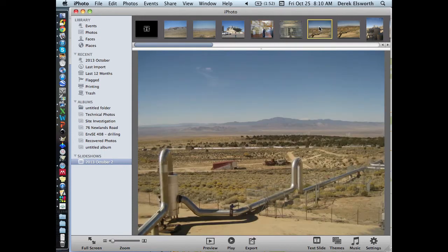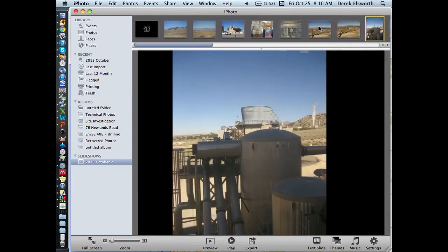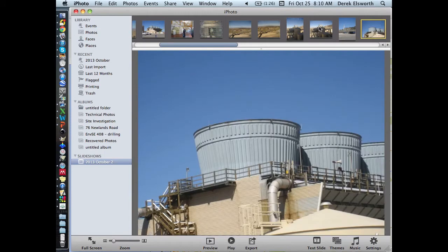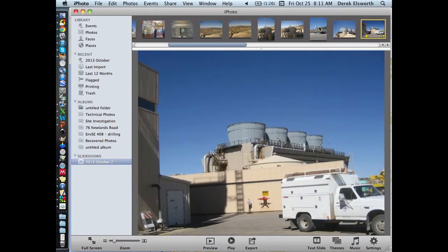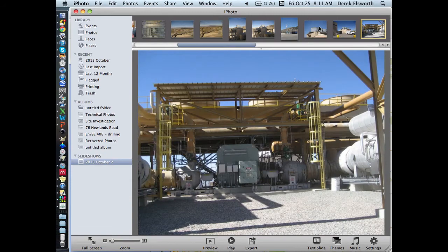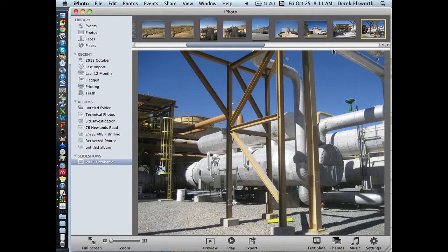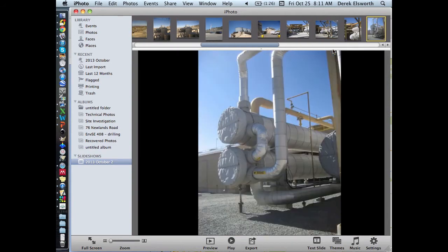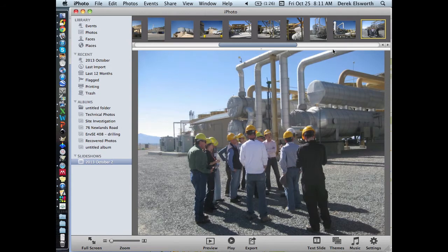It's very clean. So there's this, and the well pad. This is the steam plant. The high quality steam goes through, which has the most heat capacity. This is the binary plant, which uses a closed system of isopropanol to be able to evaporate and run through a turbine.